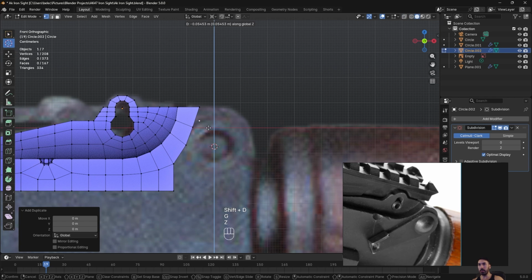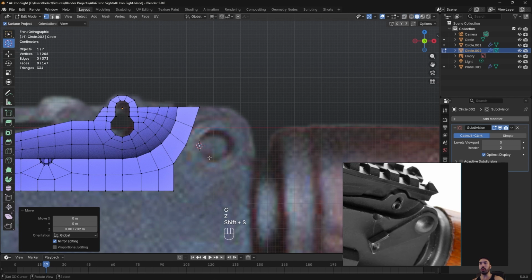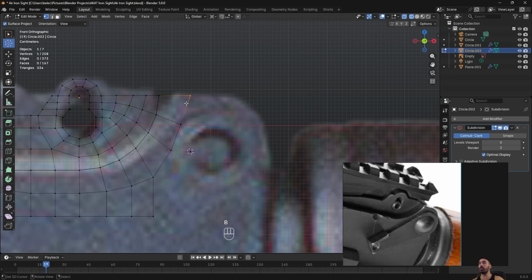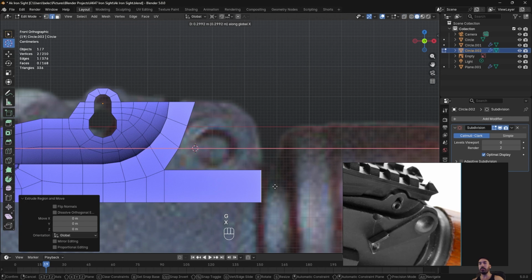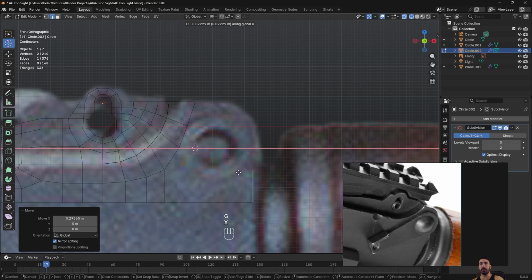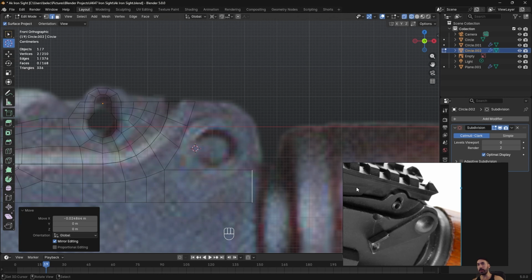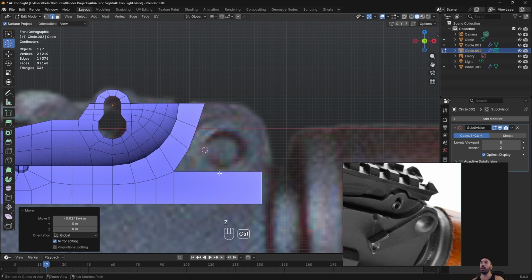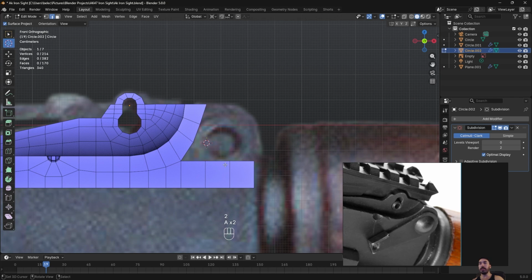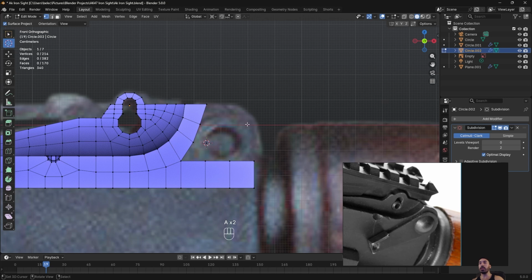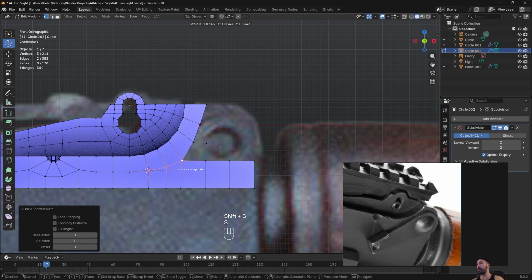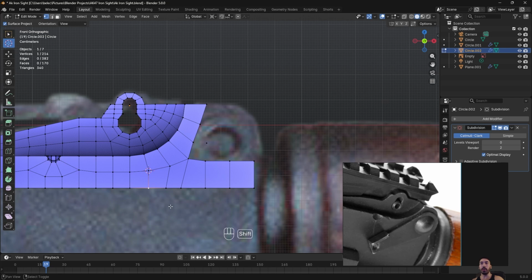So let's take this vertex, we're going to push it down here, place the cursor onto that vertex, take this vertex over here at the top, and here's what I'm thinking. I'm thinking we're going to take this edge segment and push it to the end, although I think the end is supposed to be a little bit further back if we look at this image and not the background image. And we're going to have 2 loop cuts here, and then the idea is we have 3 edges at the bottom, 3 edges here, and if we have another 3 edges here, that's going to allow us to create a circle with 9 vertices. That is simply the best that I could come up with in my 2 hours of trying to do this that I was complaining about at the beginning of the video.